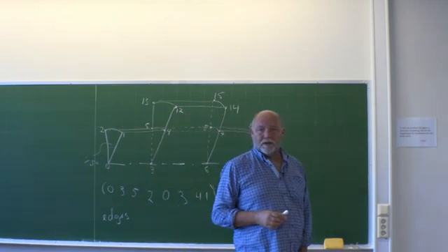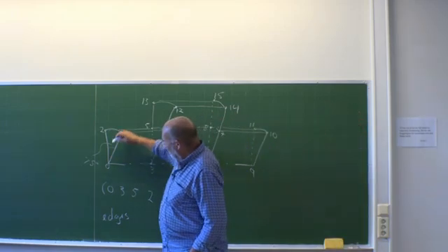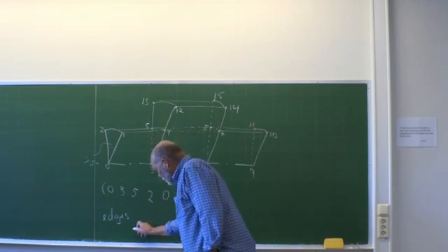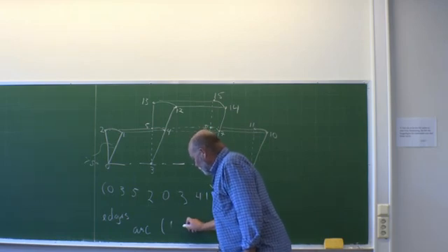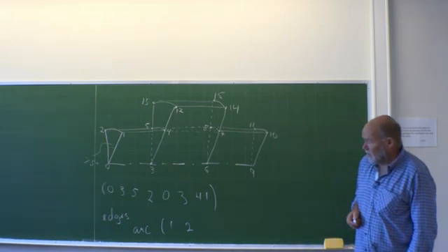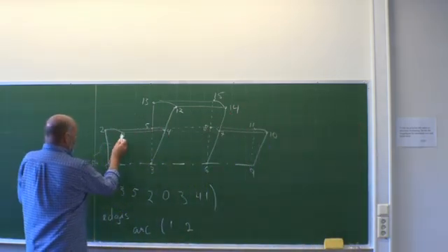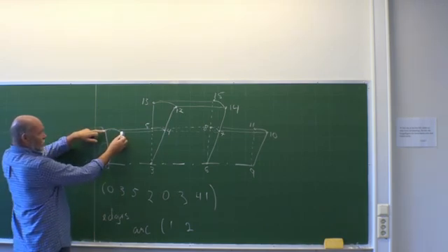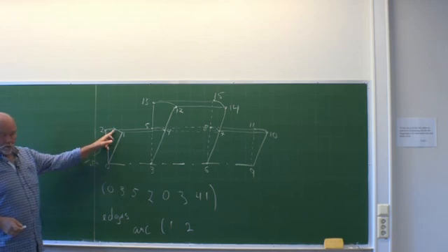And how do you do that? Well, you use an arc and you state from 1 to 2. So it should read something like this: arc between point 1 and 2. And then you need to specify a point. It already knows these 2 points. You just have to specify a point on a surface here.